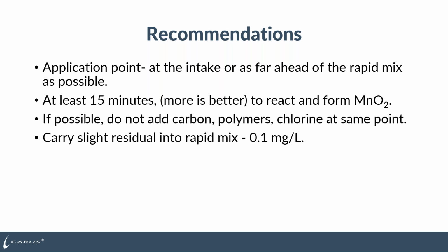Now, why would I say not to add carbon, polymers, or chlorine at the same point? In the case of carbon, carbon can absorb organics, but carbon also absorbs permanganate and neutralizes it. So if you feed the two at the exact same time, some of your permanganate is going to absorb onto the carbon, and so you're going to lose some of your permanganate to a neutralization reaction with the carbon. And as that carbon reacts with the permanganate, you lose some of its ability to absorb organics as well. So if you separate the two out, it's a more efficient use of both chemicals.